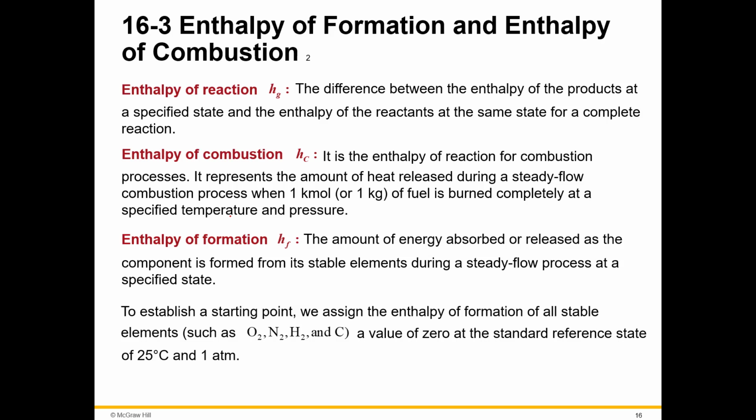The enthalpy of combustion, h_C, is the enthalpy of a reaction for combustion processes. It represents the amount of heat released during a steady flow combustion process when 1 kilomole or 1 kilogram of fuel is burned completely at a specified temperature and pressure.